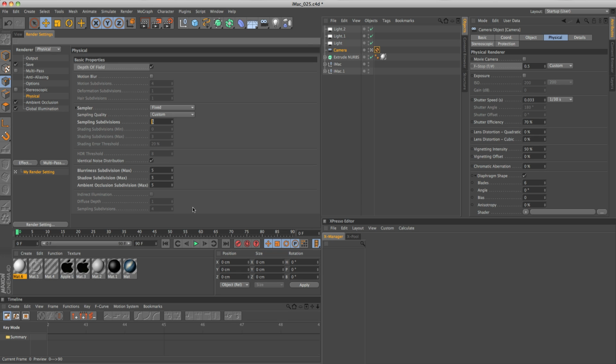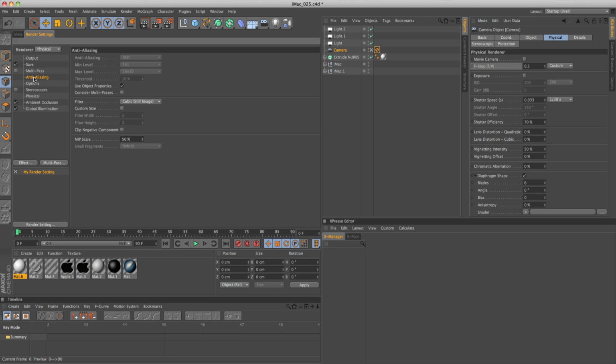So if you wanted to bump this up, the render that I did on my Facebook, like I said before, was 10. So if you bump that up to 10 and see how it goes, and if not, you can always lower it down. And the last thing that I'm going to do is just show you how to render it out to an actual picture. Oh, and there was one thing, if you're using the physical rendering, what I like to do is change the filter under anti-aliasing to Mitchell, and that gives you a really nice sharp anti-aliasing.